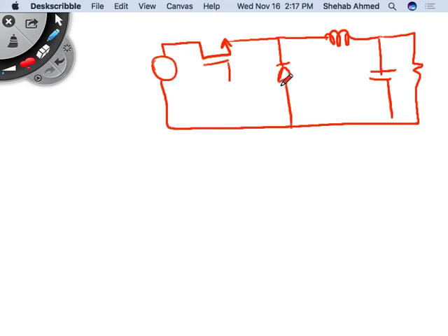We said that initially we didn't have this diode at all. We had a switch and an output resistor, and we said we'll open and close the switch. But then this makes the output current discontinuous. So how do I make the output current continuous? I put an inductor. But if I put an inductor there and open the switch, I will have very high voltage across the switch. That doesn't work, so I have to put a diode. So we created the buck converter that way.